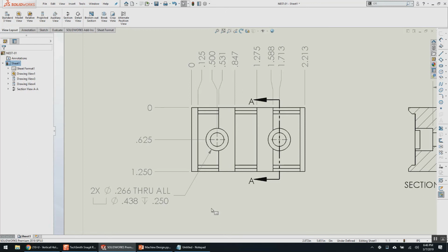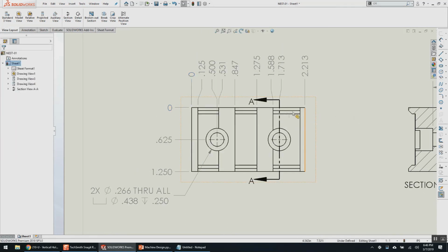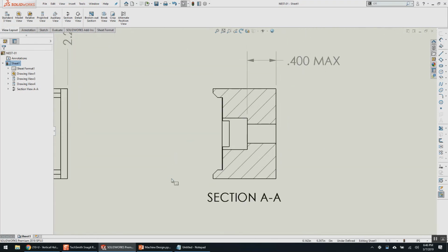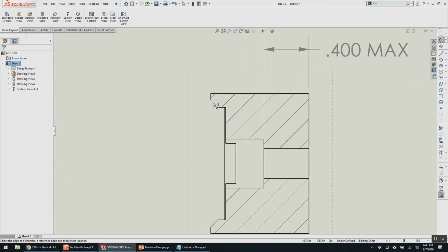So you typically put the part in the vise, move it to the left to your 0. And if you consistently set up your prints this way, then your machinists don't have to pick a new zero every time they want to make a new part. If you've ever been a machinist, talk to a machinist, have sympathy for machinists, you will understand that concept.